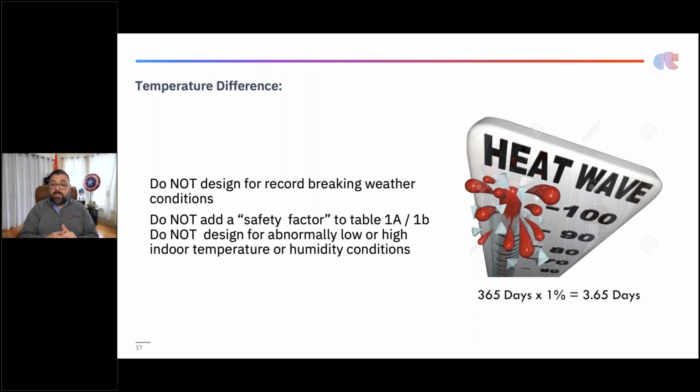And don't get me wrong, the correct size heat pump or furnace or boiler, whatever you're installing, is going to run all the time to try to maintain temperature. This happens in the northern reaches of Maine and the highest points in Minnesota. And we have heat pumps, like I was telling you before, I work at Mitsubishi. We have heat pumps as the sole source of heat. They work great because they were sized correctly for that building at that really low extreme temperatures down to as low as -13 Fahrenheit. All right.